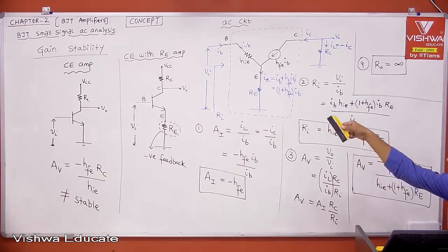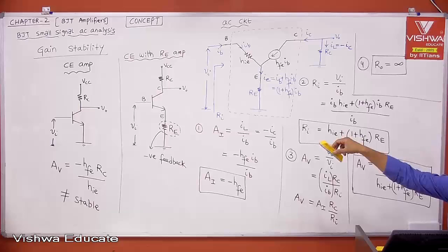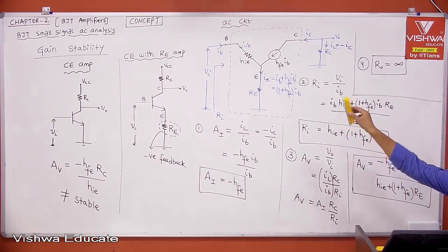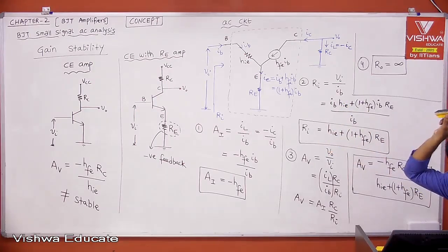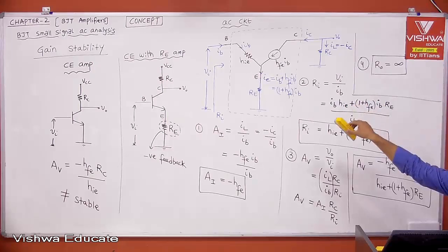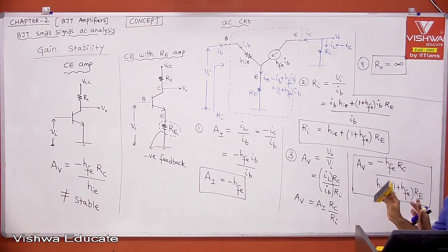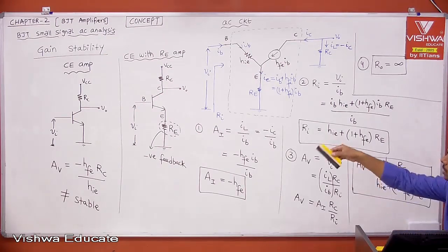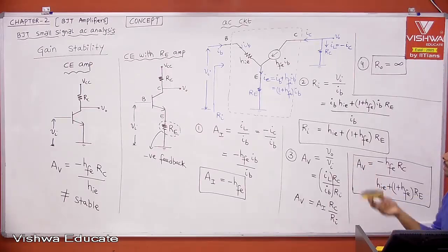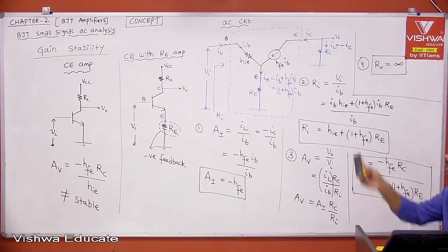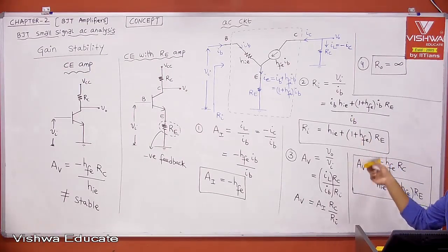Because of that extra resistor RE, we should not use those formulae, right? Because the common terminal should be grounded. That is what we had seen and then we derived. But here the common terminal is not grounded, it is having some RE, that's why we derived once again. Once you understand the derivation, how many times you want we can derive. We can replace the BJT with the proper model, whether it is the simplified model or the exact model. Here we used the simplified model and then we continued, then we got all these 4 AC parameters.